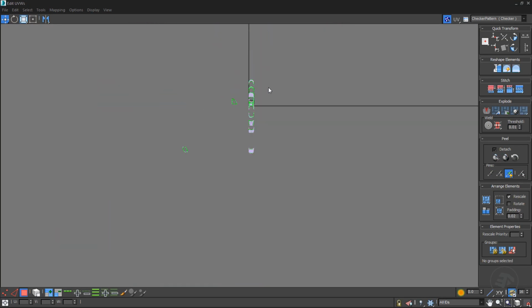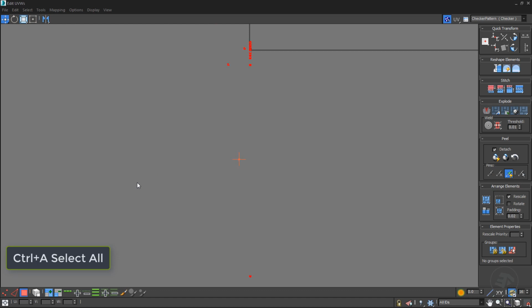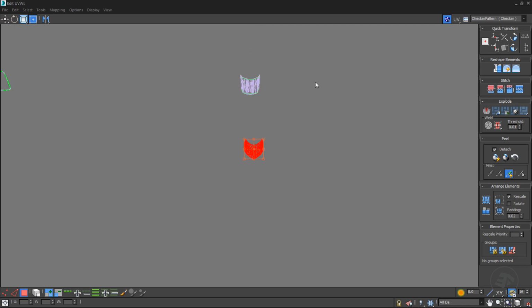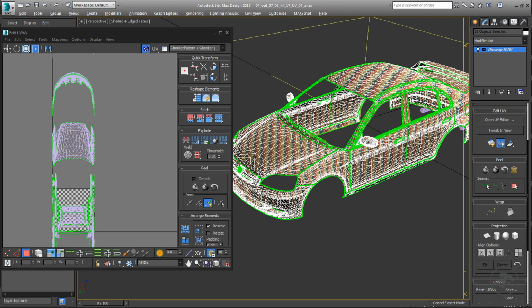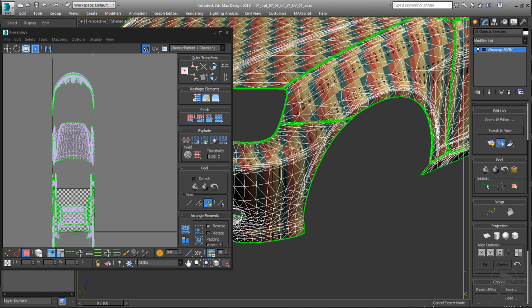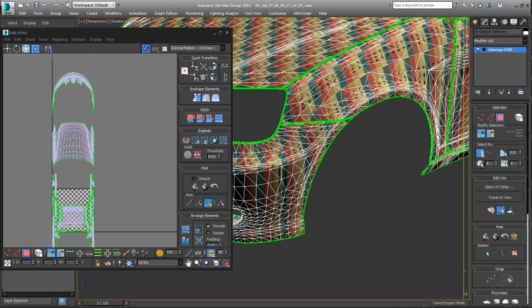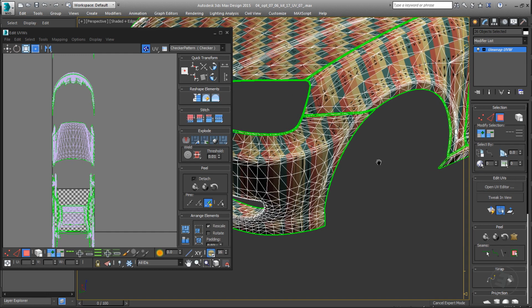What you see now is the original UV map that was created automatically by 3ds Max during the designing stage. We need to unwrap these original UVs to be compatible for video games. Let's select the left and right side. Disable Ignore Back Faces to speed the selection process.